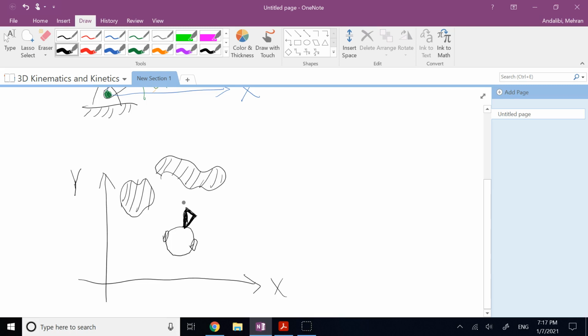So how does it do it? Well, this robot sends its signal, acoustic, infrared, whatever it is, to the different points on the object. It bounces back, it basically receives the reflected signal, and then based on the time of travel measures the distance from here to here. And then at this point the robot knows that it has rotated so much with respect to the x-axis.